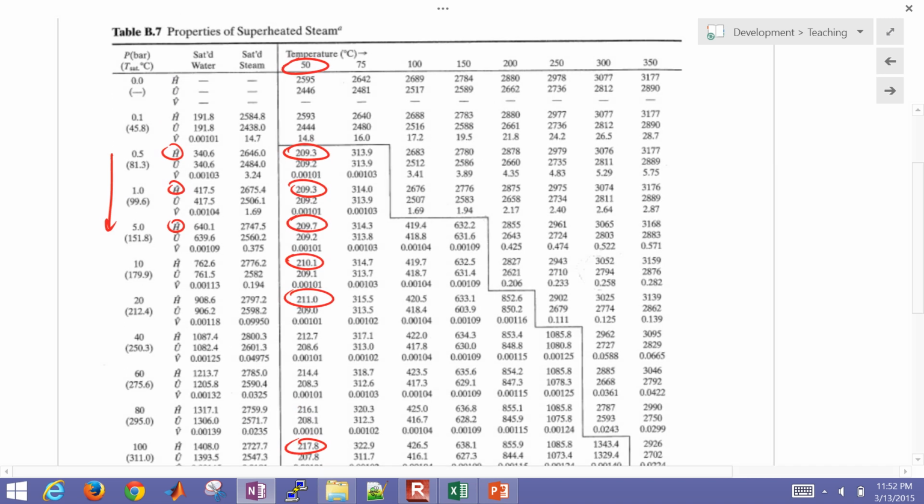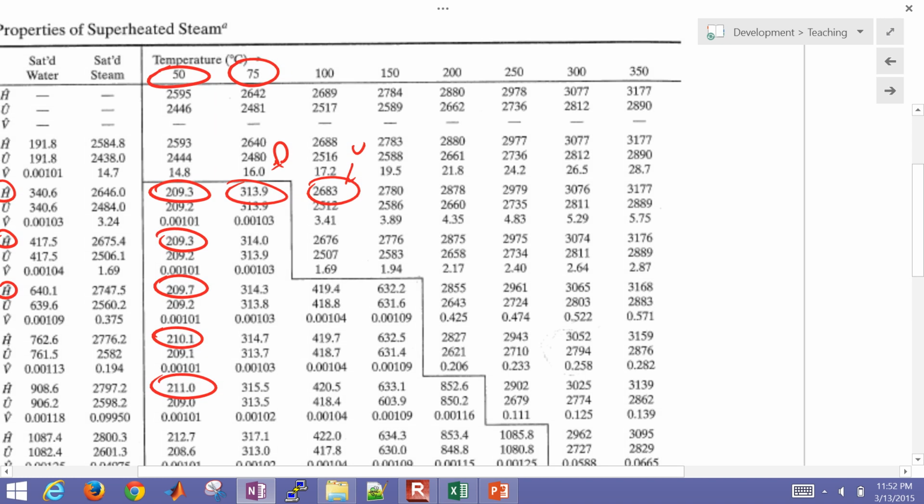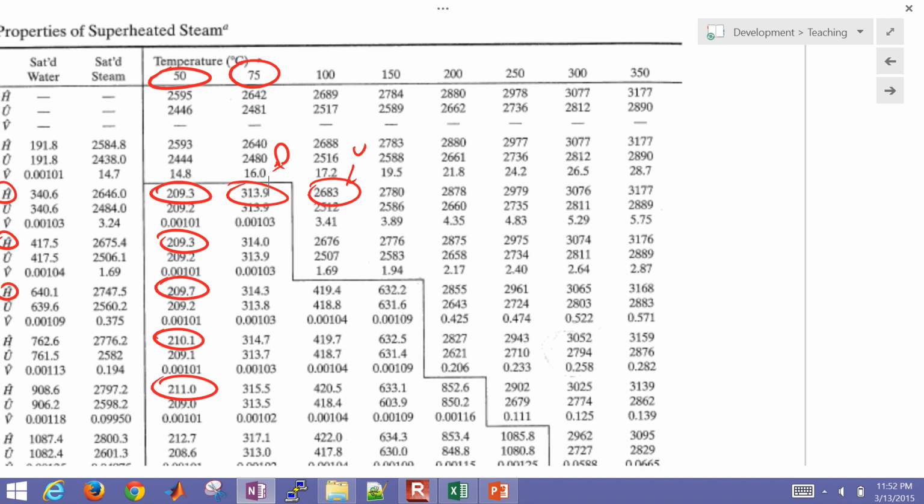So let's say we go up 25 degrees. You can see this goes up, and this is vapor now. So phase changes and temperature, those are the big effects on enthalpy. Pressure is just a very small effect. Let's also look at its effect on vapor as well. Here's the enthalpy of vapor at different pressures, and again, not a big change in the enthalpy.